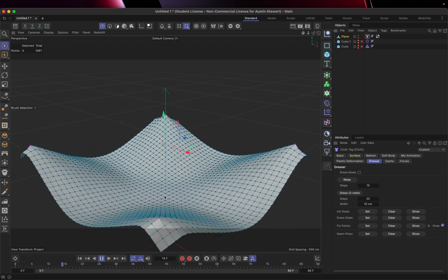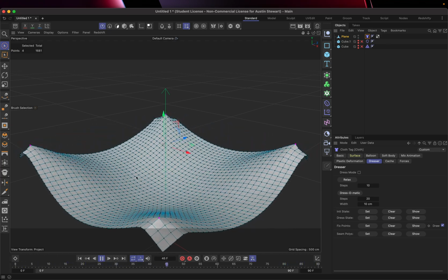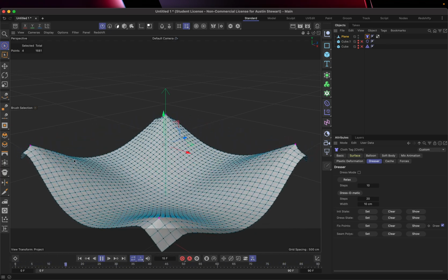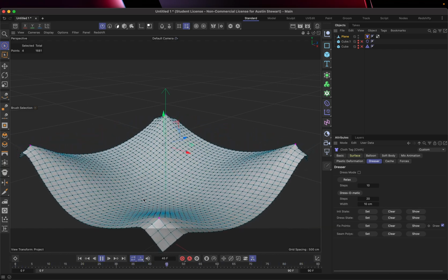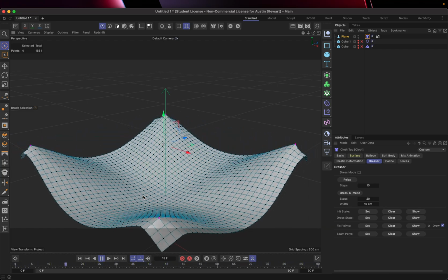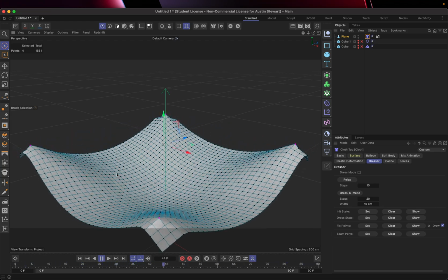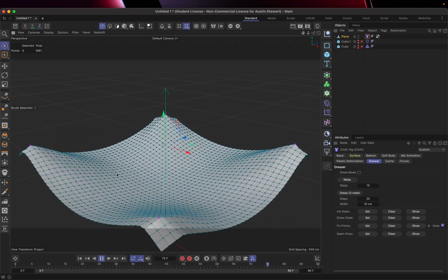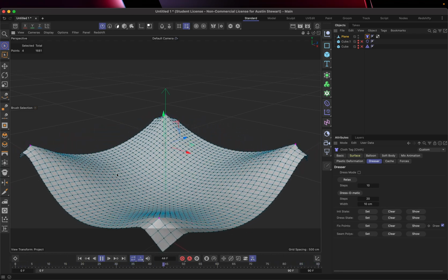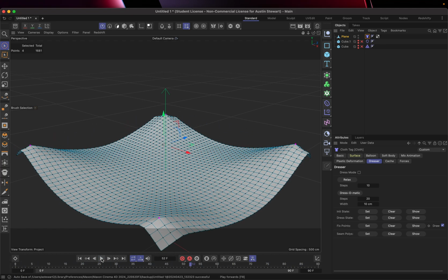Also, if you're having some collision issues with, say, a cube that you're using as a table, you could basically pin your points just above the tabletop in the corners to try and keep that from going through. There's other ways you could set some settings in the physics engine to make that nicer, but we're not going to worry about that right now. We're just looking at how we get these basics done. So, we've got our cloth pinned up.